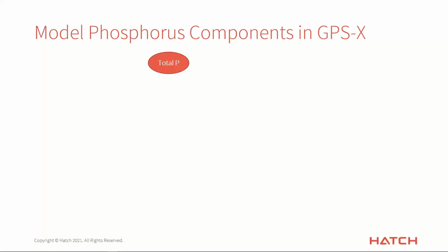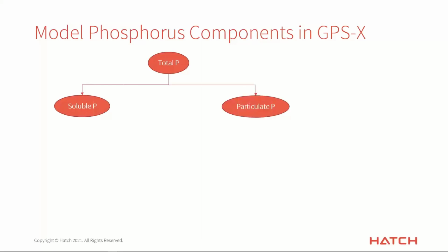So obviously the total phosphorus that we have in the system is made up of a number of different types of components. And the way that these ASM models work is that we do mass balance for each step in the process, like for each reactor, on a number of different forms of phosphorus. And then all of those things might not be able to be measured directly or typically measured directly. So we add them up, and in the end, you come up with something like total phosphorus. But in reality, in the model, total phosphorus is actually made up of soluble P and particulate P. And in fact, these are also broken down into further categories that we actually do predictions on.